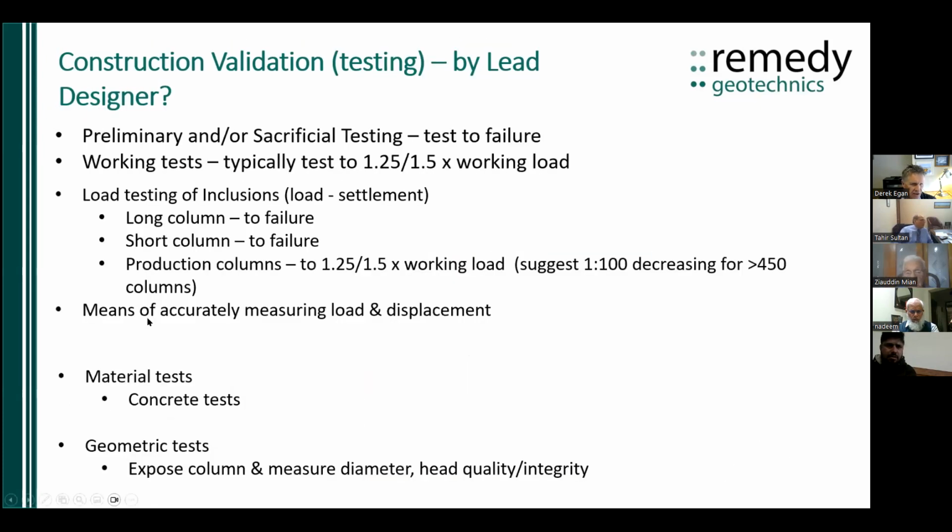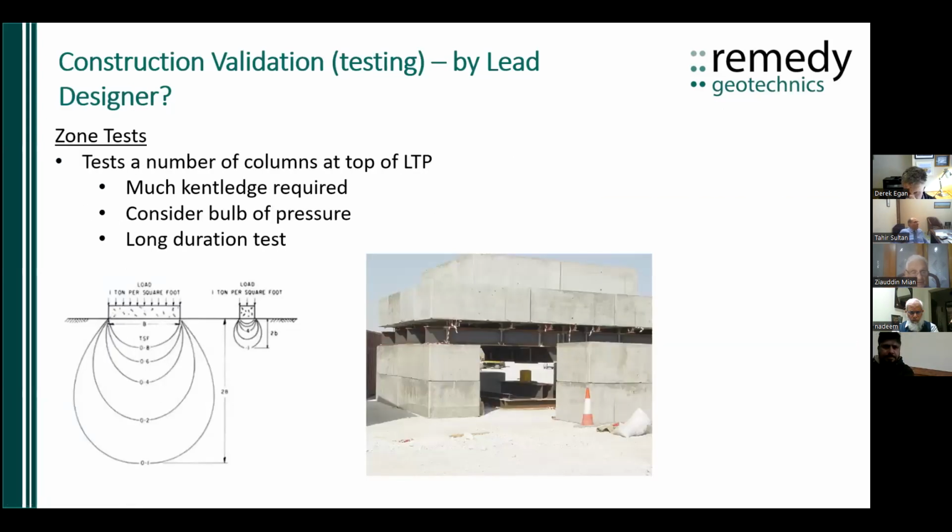These individual tests are more like a pile test, or can even be done with a plate loading test type setup, where you expose the top of the head and just put a plate on it and put the load on, because usually the load in the column is not going to be high, maybe 100, 200 kilonewtons. That's maybe 20 tons, and you can use a rig on site as the reaction.